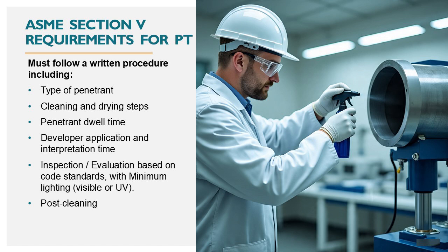The surface of the part to be tested is cleaned to remove dirt, grease, and other contaminants that could interfere with the test. Penetrant dwell time. The penetrant is allowed to dwell on the surface for a specified time to give it a chance to enter any small surface openings through capillary action. Developer application and interpretation time.